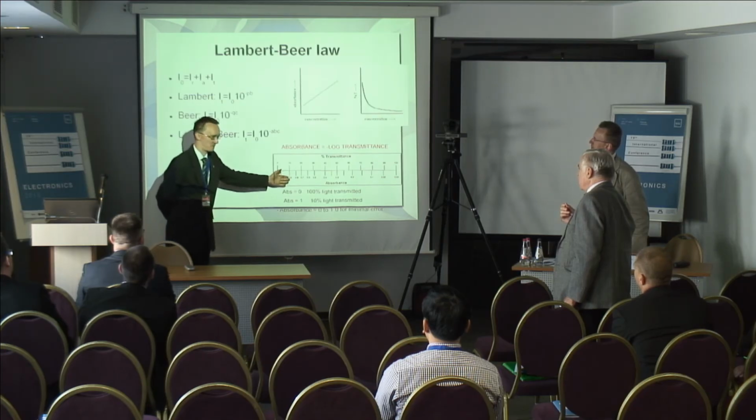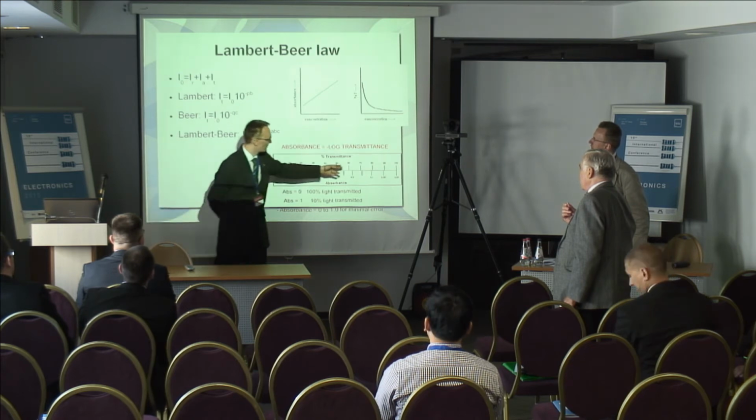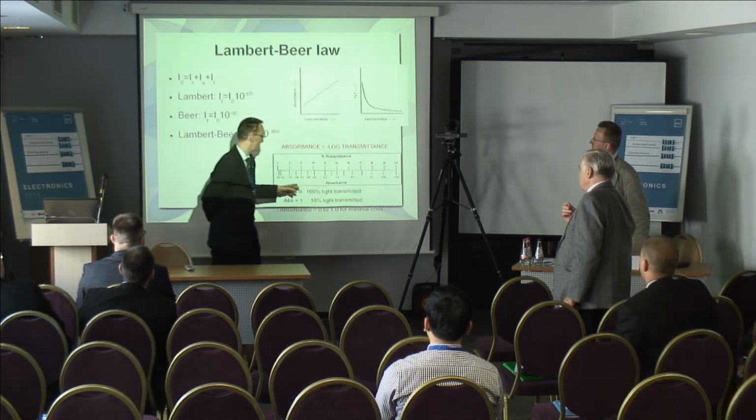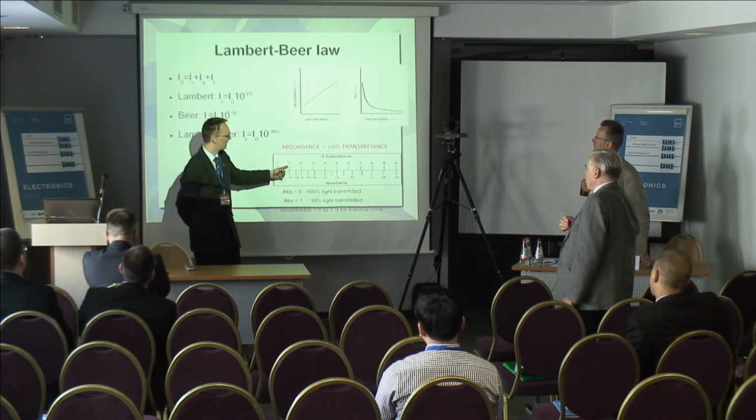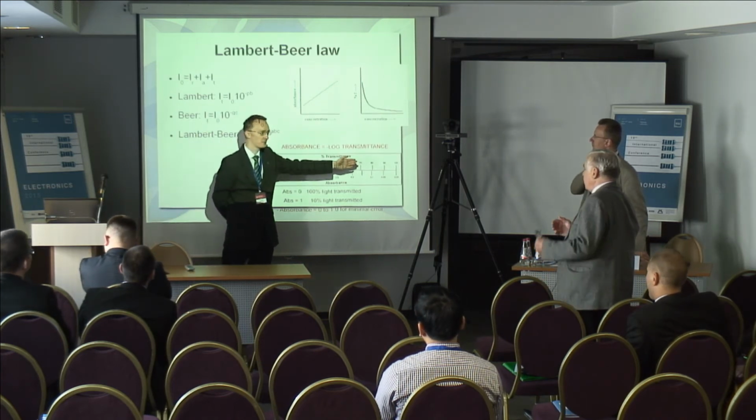You try to check the transparency of the water, right? Transparency of what it is. Well, we usually say transmittance. Transmittance, which corresponds to absorbance. Yeah. So 100% transmittance is no absorbance. Okay. As you can see here, we should work between 10% transmittance up to 100.